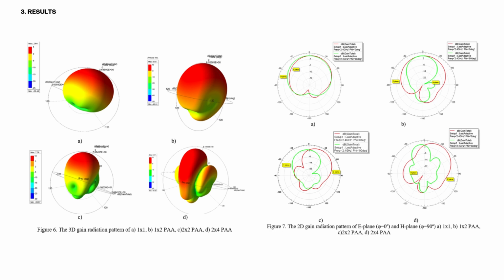And it can be noticed that the H-plane in each plot has a similar trend, where increasing the number of patches leads to a reduction in the width of the main lobe and the appearance of additional side lobes. For 4-element and 8-element PAA configurations, the E-plane exhibits a more focused main lobe with HPBW of 52 degrees, ranging from minus 5 to 57, and 61, spanning from 4 degrees to 65 degrees, respectively.